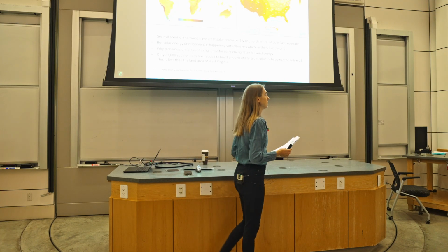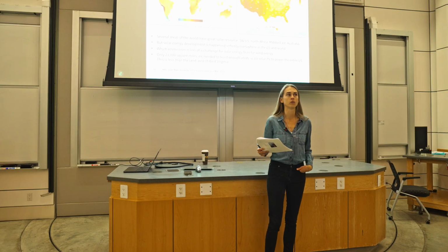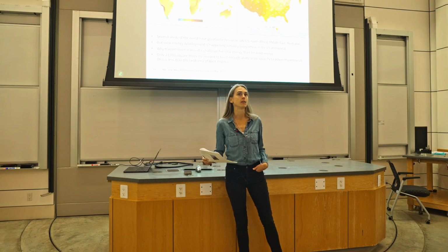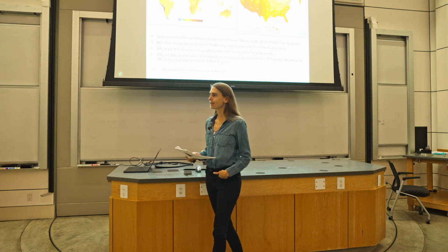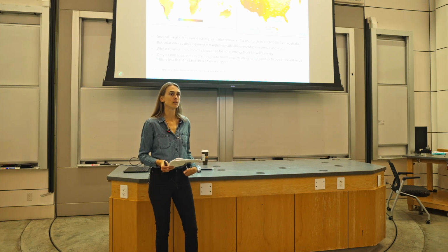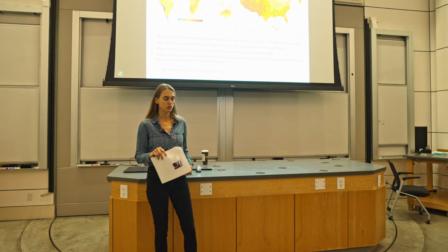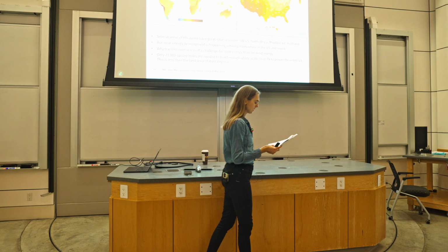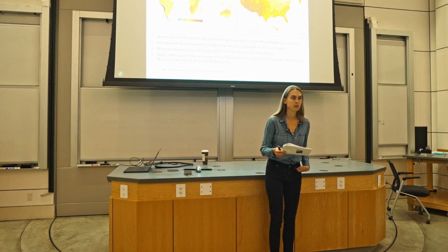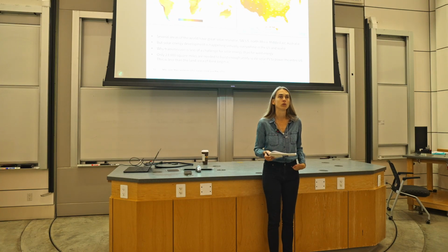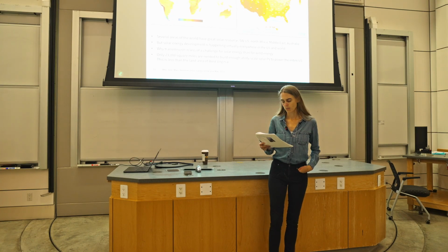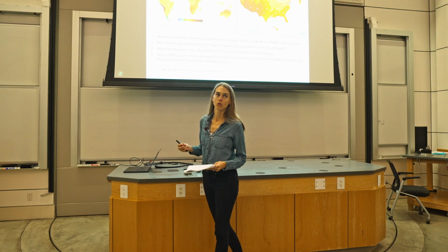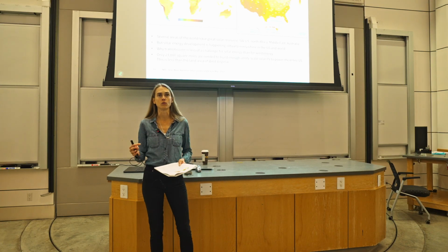But if it's a fully cloudy day where you've got 100% cloud cover, you can't see the sun, then that's 100% diffuse radiation. And this is significant in the context of energy because some solar technologies can take advantage of both, and some can only take advantage of direct. So solar PV can capture energy from both diffuse and direct radiation, but technologies that use reflectors and mirrors, like concentrating solar power, can only take advantage of direct radiation.